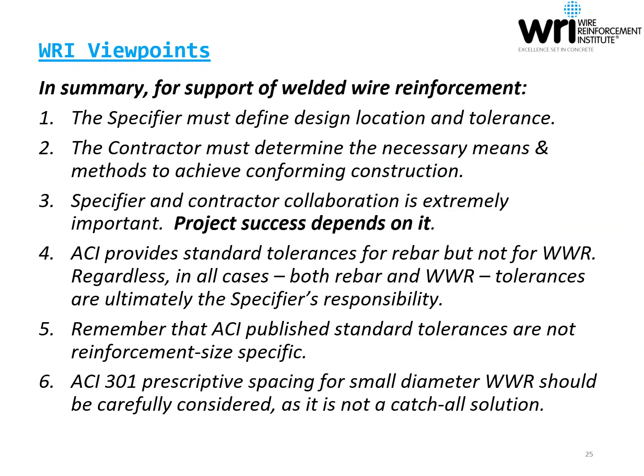In summary, for support of welded wire reinforcement, the specifier must define design location and tolerance. The contractor must determine the necessary means and methods to achieve conforming construction. Specifier and contractor collaboration is extremely important. The project's success depends on it.